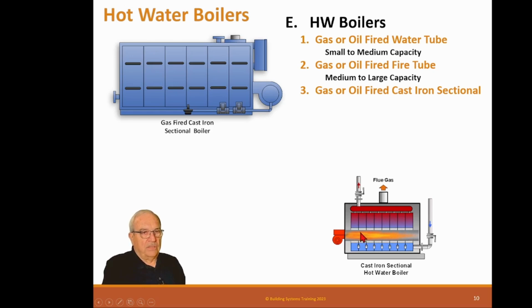So in this one, the fire goes down the middle and out around and goes out the flue, and then the water goes out this way. These are also in a situation where you don't have to worry about that leaving temperature. Well, you might on this tank, but it's not like a fire tube, which the tubes are always in water. These always have water on the inside. They have nothing on the outside. So this we probably need to control the temperature like we do on the water tube.